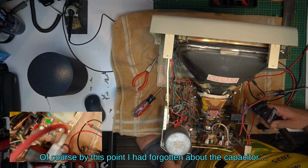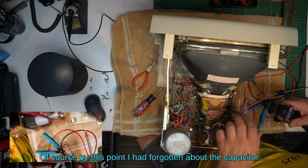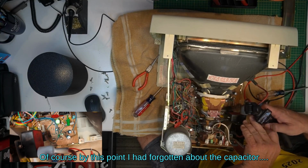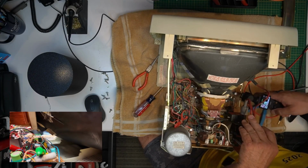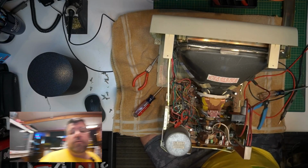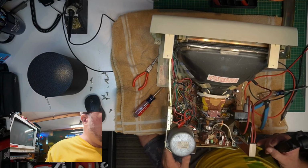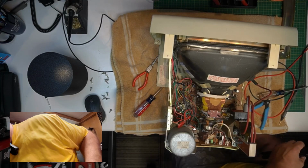So what I did here, to get all the high voltage wiring out of the way, is I jumpered that chip. I don't know if you can see it there. There's an angle we can maybe work with. I put some jumpers on that chip, pins 17 to 22, on the suggestion of the manual that if I jump that and I get deflection, then I have a bad chip. Seems like an easy thing to test.